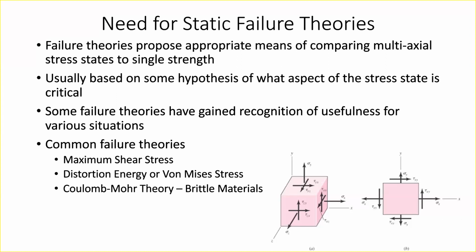The intuitive way of understanding that is if you have a super brittle material, you'll typically fail in what's called crack propagation. Brittle failures happen extremely quickly because there's not much elasticity in the part. So if you put a brittle part in tension, it'll be much more likely to fail than the equivalent stress in compression, right?